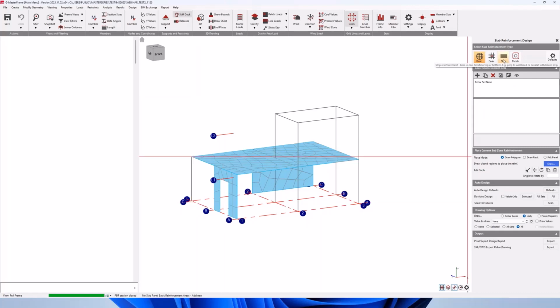Strip reinforcement is intended to provide enhanced reinforcement in strips where higher bending moment occur along lines, for example, within column strips in slabs. The strip reinforcement provides options to define reinforcement in either the top or bottom of the slab, and also whether the reinforcement is orientated parallel or perpendicular to the strip lengths. Strips provide option to define reinforcement in one direction only.